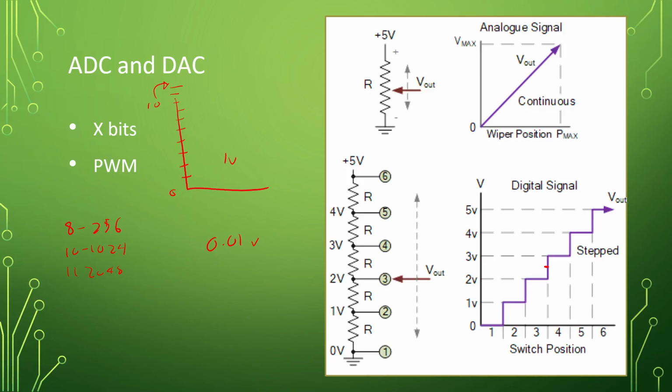All right. And let's say we need to read, again, 83.4 degrees. Well, if we had a thermocouple or a temperature sensor that could read between 0 and 1,000 degrees, and again, we only have 1,000 steps, we're still only accurate down to 1 degree. But if we have a temperature sensor that only reads between 80 and 90 degrees, and we have 1,000 bits, that's 10 degrees over 1,000 bits. We have lots of accuracy. Right? So not only is the resolution of your analog to digital converter important, so is the resolution of your temperatures. All right. So there's a lot of games that you have to play when you're picking an analog sensor.